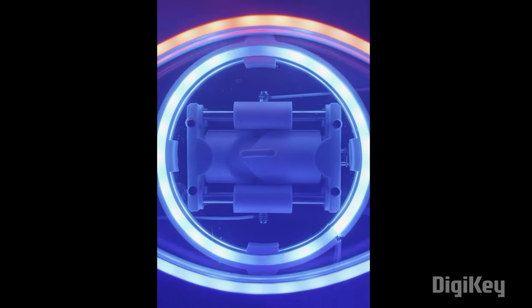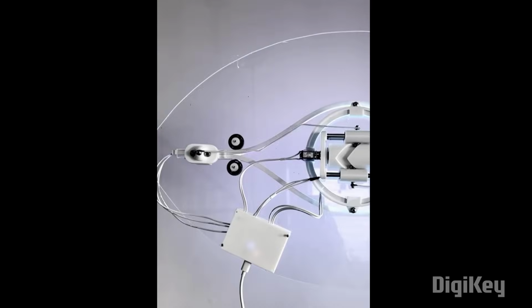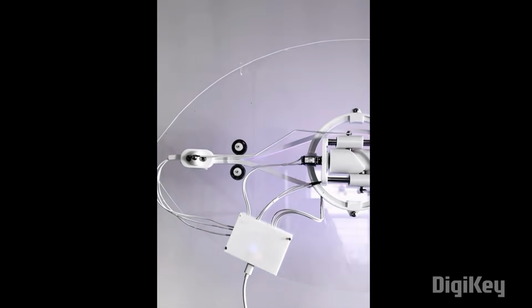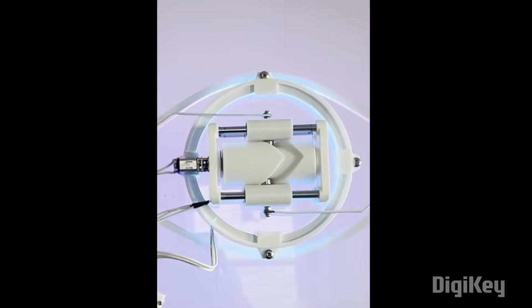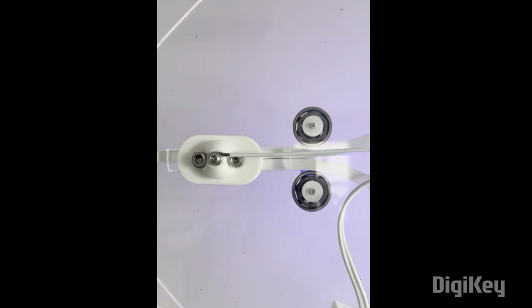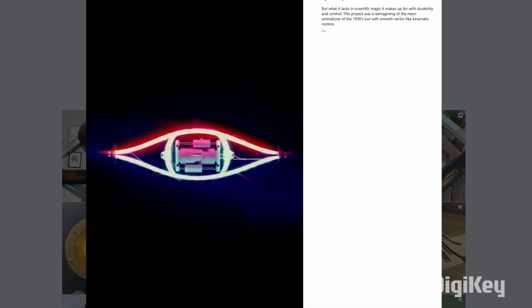And finally, I got a kick out of seeing this LED neon animated eye by David Hamp-Gonsalves. This is such a cool effect. For the mechanical movement of the LED neon strip, there's a 3D printed reciprocating barrel cam that's driven by what looks like a geared DC motor. This pushes 2 linear bearings back and forth attached to push rods that push and pull on the ends of the LED neon strip, opening and closing the eye.